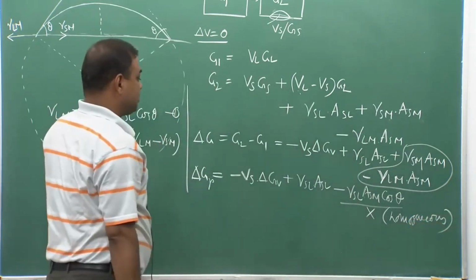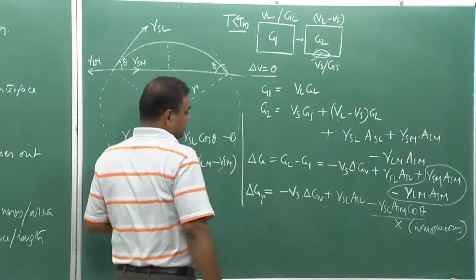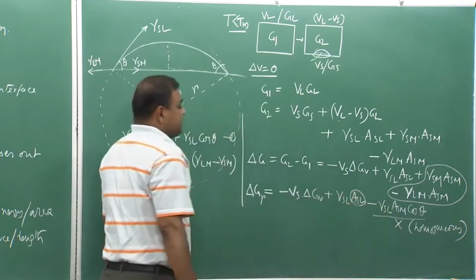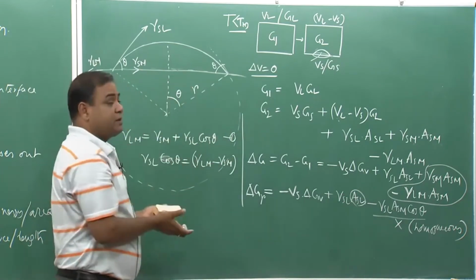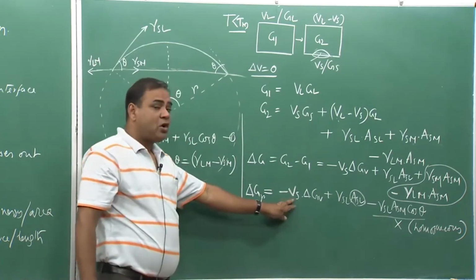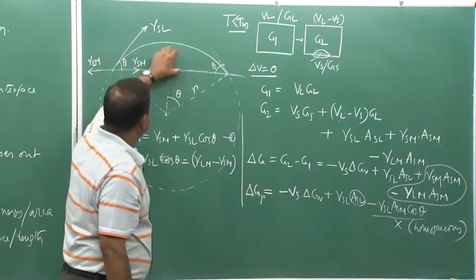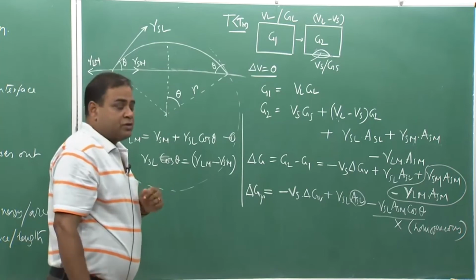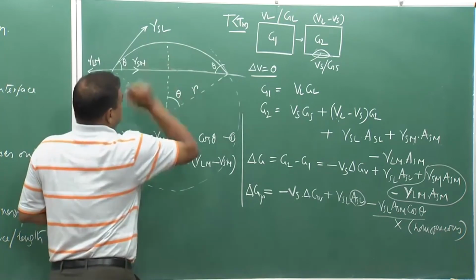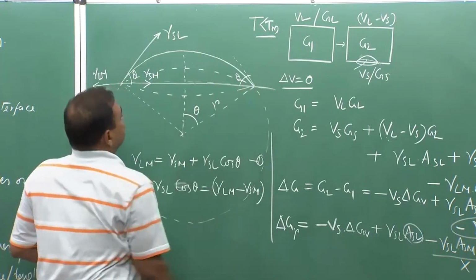Homogeneous nucleation was not there, but in the case of heterogeneous nucleation, that means when we have a mold surface where the solid is forming, we have this creation, but this particular area is also not the total surface area of a sphere, rather part of that surface area. At the same time, this Vs is not 4 by 3 pi r cube, rather this is the volume only of this particular portion, not the entire portion. So the entire problem lies in the calculation of this volume and the surface area of this particular region.